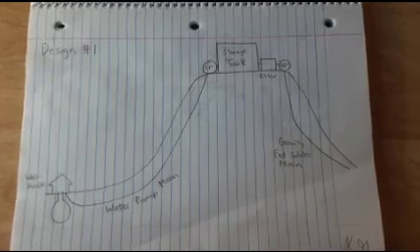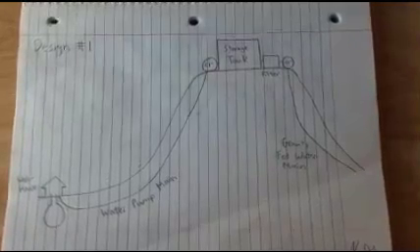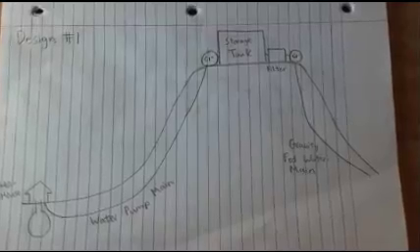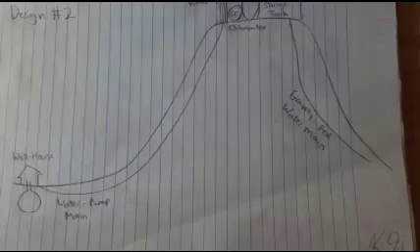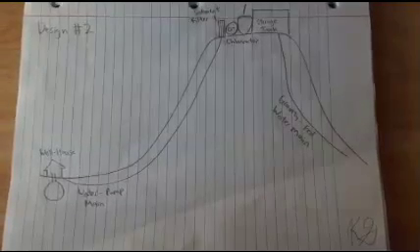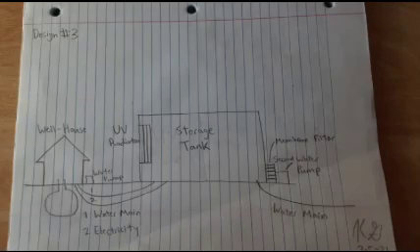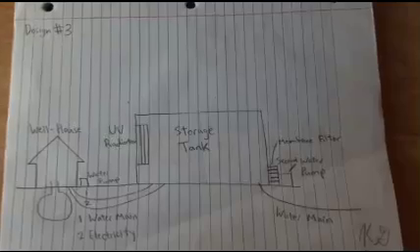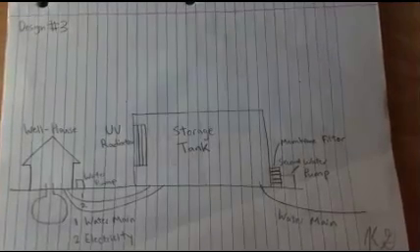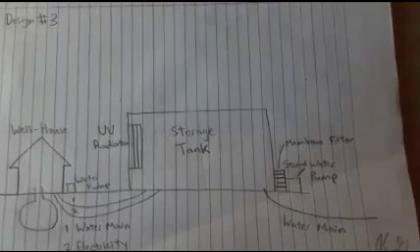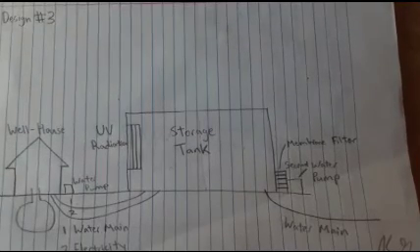Our first design alternative was a double chlorination system, which is the system that we chose as our final design. This design uses chlorine pellets and micron filters, which is discussed further in this presentation. Alternative 2 was a reverse osmosis system with chlorine pellets, but this design alternative was much too pricey. Design 3 was based on UV light exposure and would also need a filtration system with a membrane filter. The UV filters would be very hard to replace, making alternative 3 impractical.